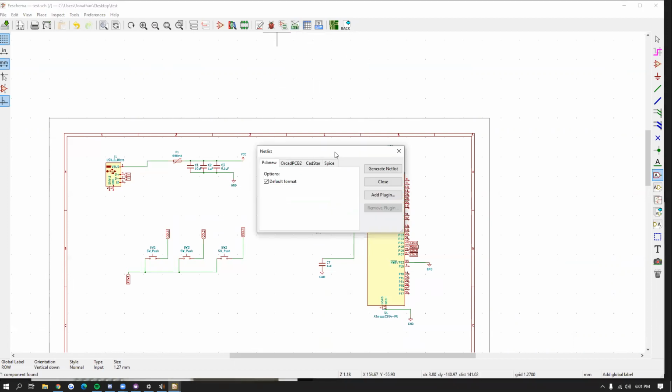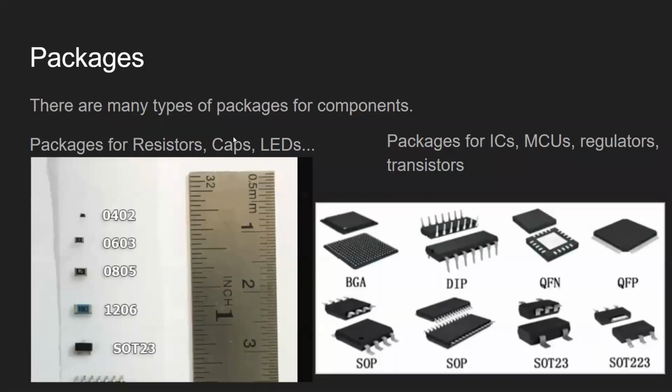Real quick, what was the name of the resistor that you used? I forgot. I think I used a 1206. And is it a through hole or an SMD? When I say 1206, it always means SMD, because these are not through hole, since they don't have any wires coming out of them. It's okay if you don't get these, because I'll send you these files right after. This is mainly for you guys to get comfortable with the software. You don't have to choose everything I chose.